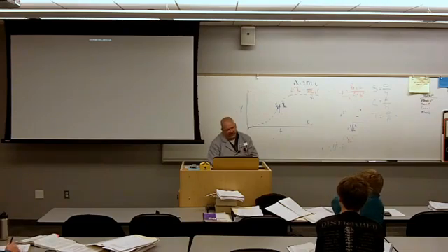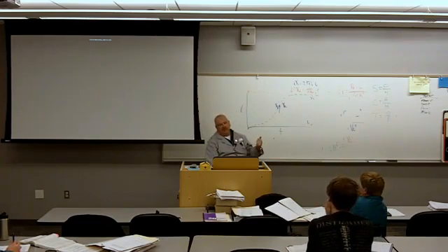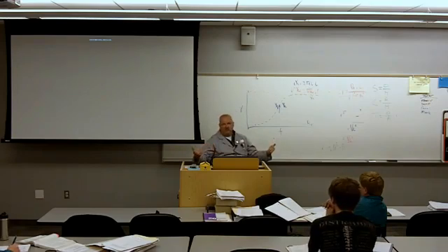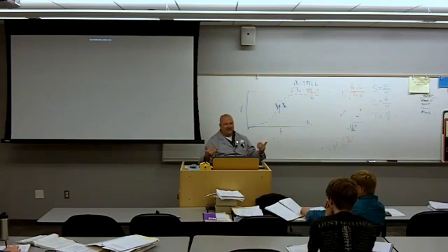Anybody have any questions on anything we discussed in this chapter? There's a lot going on in this chapter, but really this chapter is nothing more than X sub L equals 2 pi FL, X sub C equals 1 over 2 pi FC. When they're equal to each other, you're at resonance.